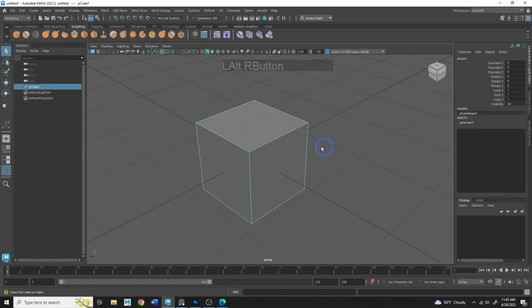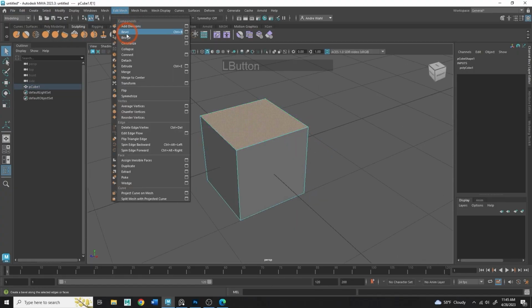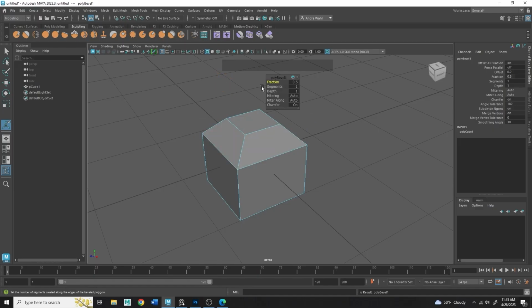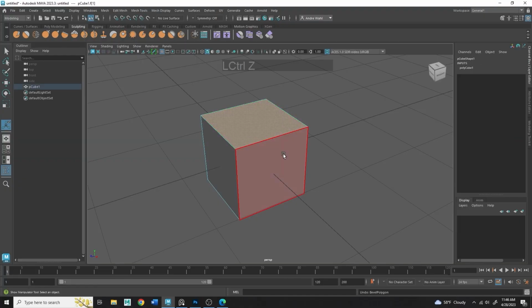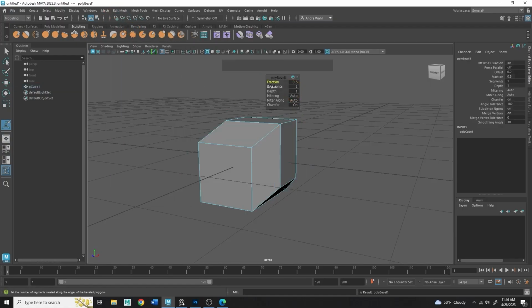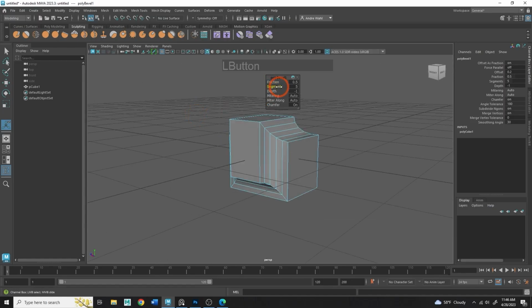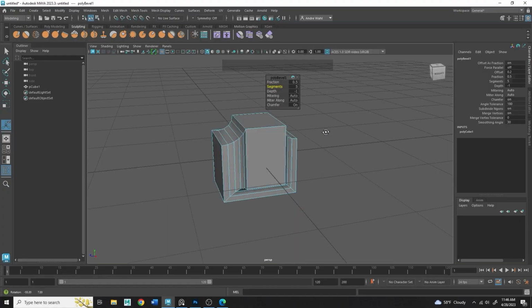Looking at other ways you can utilize this, you can select a face, and you'll see if I do a bevel, it will bevel along that surface. You have all the same controls, so you can fraction this, you can change the segments, you can change the depth, so you can see how that can be used to create a lot of different shapes. Very useful. I'm going to undo that. You can use it on more than one face at a time, so we could shift to have 2 faces in bevel, and now we're getting something real wild. Don't know what all is going on there, but hey, look at that. That's a pretty cool little sci-fi piece, right? So we can create some really nice things there.